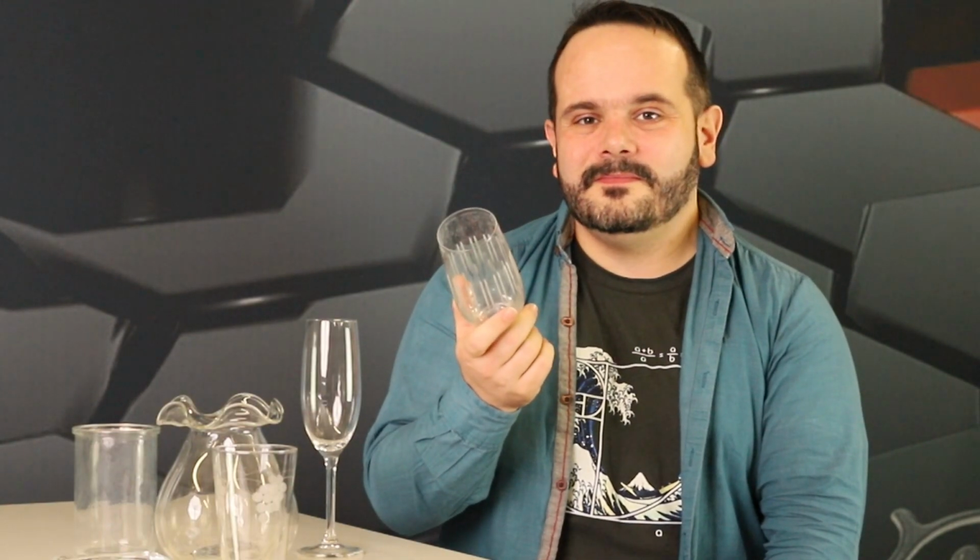Do you know how fast glass degrades? Glass degrades through four different mechanisms. Scratches, that typically appear when you touch the glass with something that is harder than the glass. Leaching, which is the glass turning whitish and not very transparent. Crizzling, which is development of small miniature cracks which can grow with time. And the formation of patina, when the degradation on the surface of the glass remains on the surface of the glass and makes it not transparent.